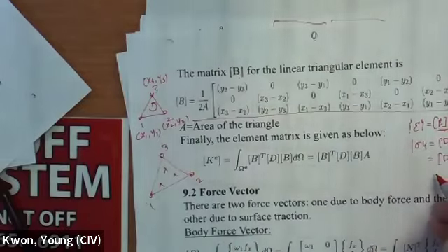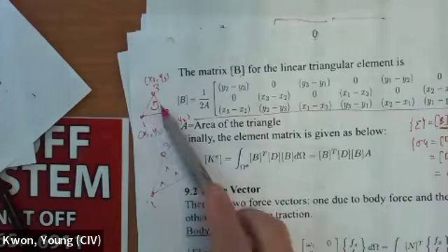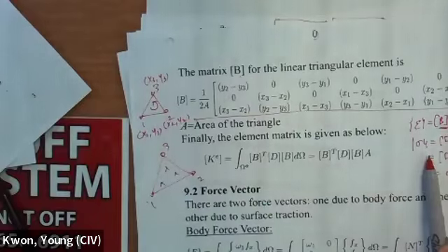So that means this is constant. That means this is also constant, because matrix T is going to be constant, at least for linear elastic. So constant. What does it mean? If I use this element, strain and stress, we are assuming they are constant within the element.